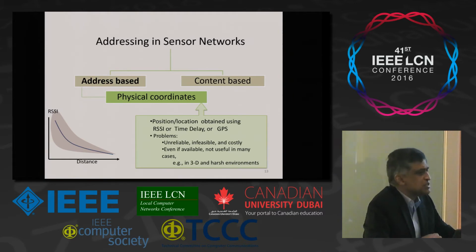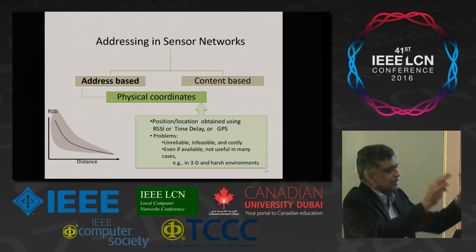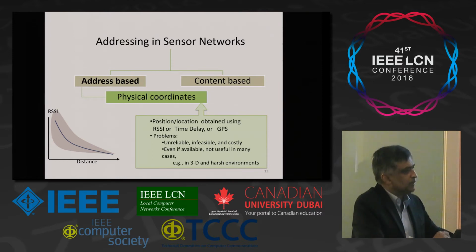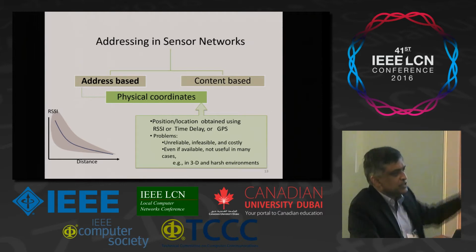When you have interference and reflections and other things, it's impossible to use. Right? I'm not saying it's a bad idea, it's worth doing research into, but I've seen places where they have used this technique and you walk into a lab and the motes are hung right between the ceiling and the floor and it works in that environment. But the moment you go to that refinery or someplace, this will not work.